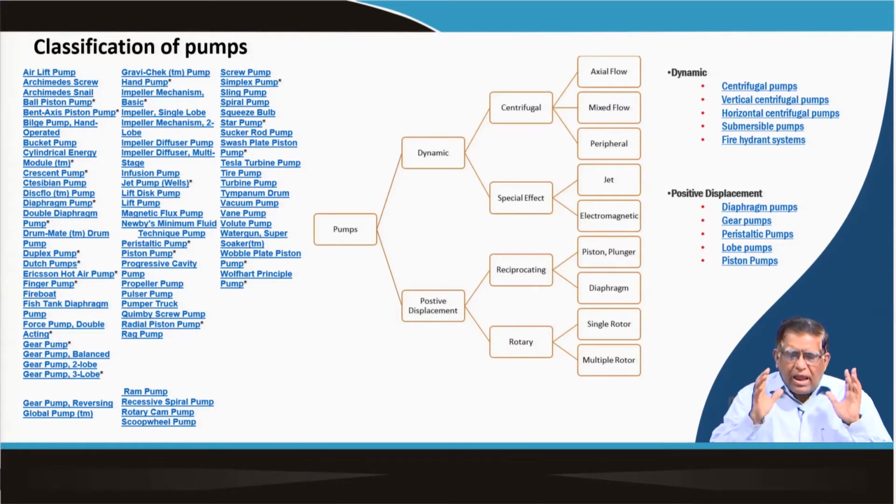So just keep in mind that pumps can be classified on the basis of how the energy is imparted, and how the flow is placed, whether the flow will be axial, or mixed flow, or peripheral, or given by a single cylinder in a reciprocating pump, whether you have a simplex, a duplex or a triplex pump, where three cylinders will be working, and whether these reciprocating pumps are single acting or double acting.